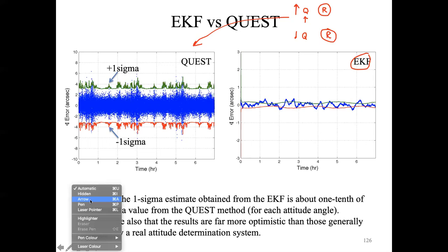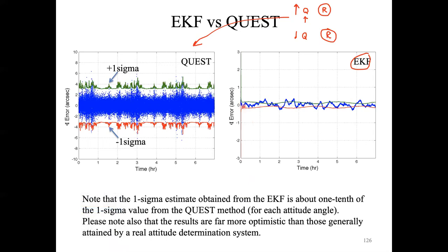But the problem here is that you're not able to provide a much more complicated formulation of the error of the gyroscope. There are possible formulations, but in principle, what is suggested is to have a short time integration step for your observation, so frequent observation from the star tracker in order to track the gyroscope. The combination of the gyroscope and star tracker measurements enables the solution that you have seen yesterday, something that tends to have an error very close to zero within the sigma.